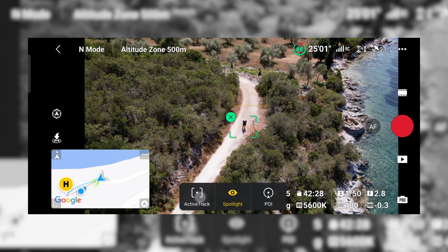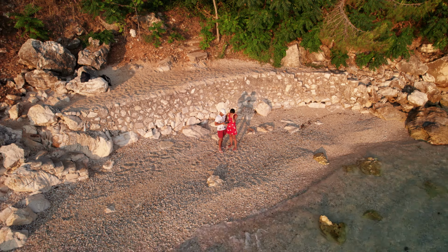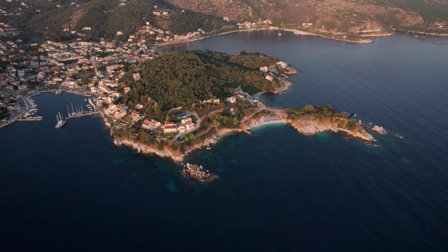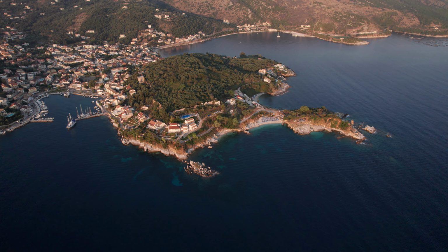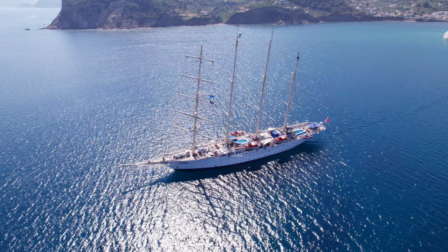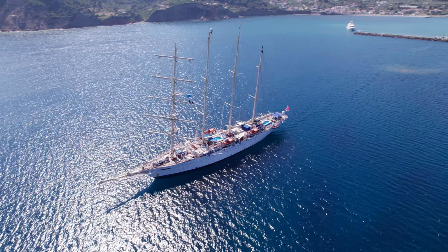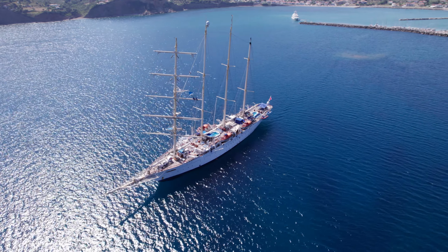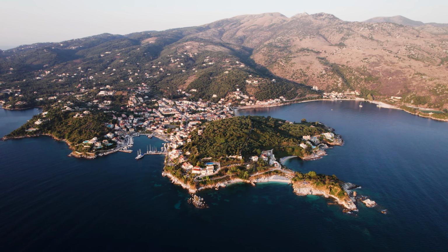Now the size is important because when the drone gets away a little bit, it might not understand anymore what is the object and what is the background. But also if you choose something that is very big in the frame, it gets a little bit confused about what parts it should actually have in the center. So you're gonna have to pick something that is in between these two sizes, and it will depend on the object itself. So you're gonna need some experimentation in the first seconds just to be sure that it's tracking correctly.